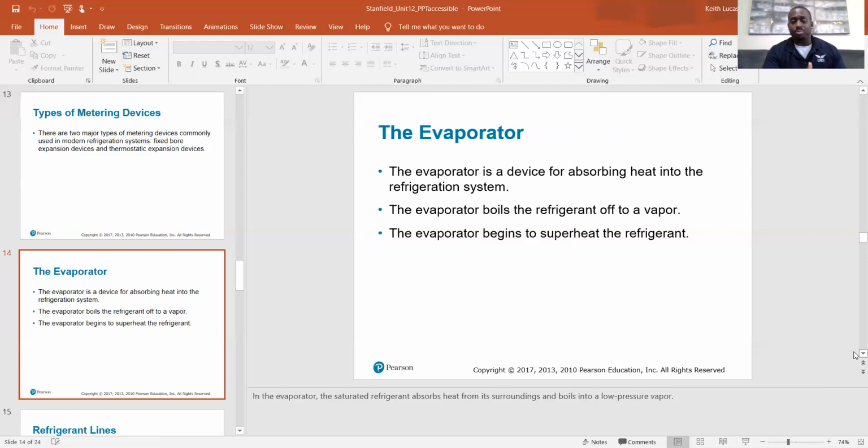That return air then has to pass across the evaporator coil. And that's where our heat transfer is going to take place yet again. So we have warm air coming from inside of the room, all the body heat that's being emitted from all the different occupants in that room, any appliances that might be running, just all the heat that's in that room is going to be getting sucked in through the return, and it's going to go across that evap coil. Now the evaporator coil's got 40-degree refrigerant in there, very cold refrigerant with some very warm air coming across it.